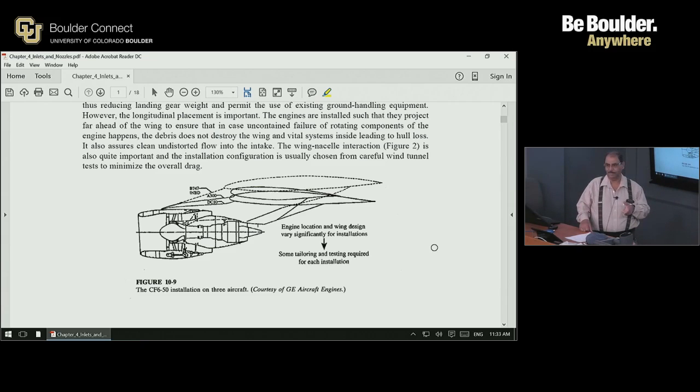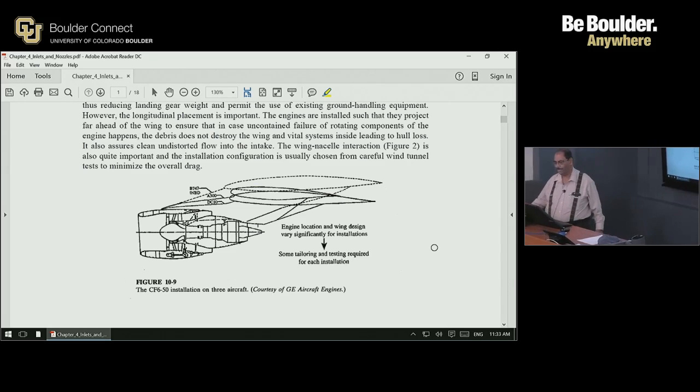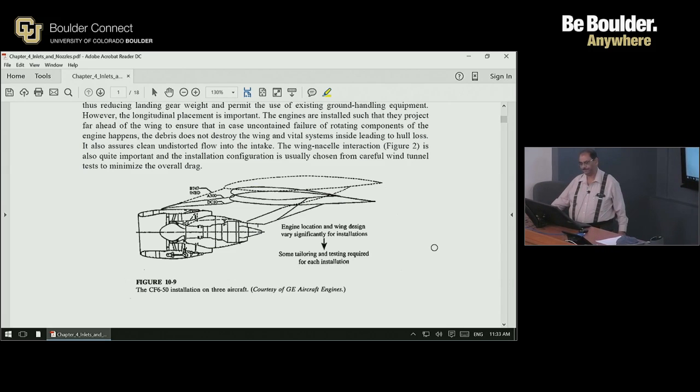Remember, the nacelle diameter is going to be significantly larger than the fan diameter. An 81-inch fan means, let's say, anywhere between 10 to 20% more diameter for the nacelle. So that's once again something working in favor of Airbus.